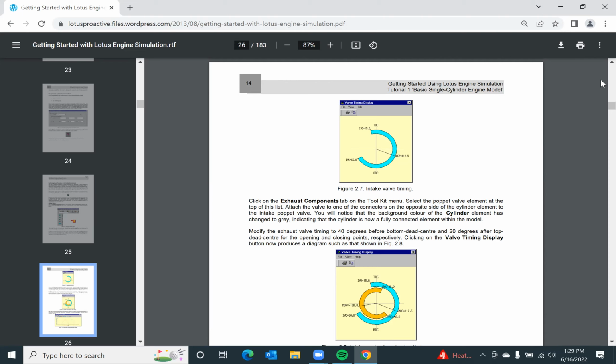That is where hemispherical combustion chambers and all that come into the picture. Because what you do is you direct the flow in such a way that contamination is minimized, and the exhaust charge is actually propelled out by the intake charge. So basically the intake charge comes in and sweeps the exhaust charge, and by the time it finishes sweeping that out, the exhaust valve gets closed.